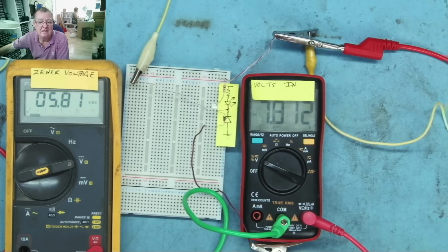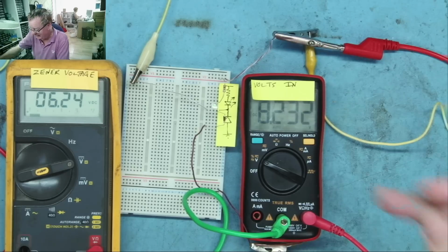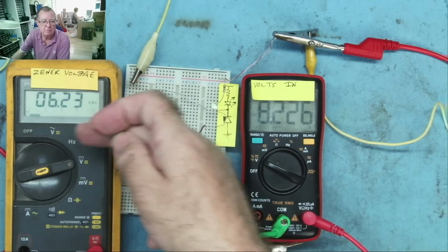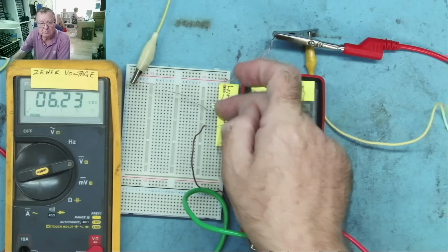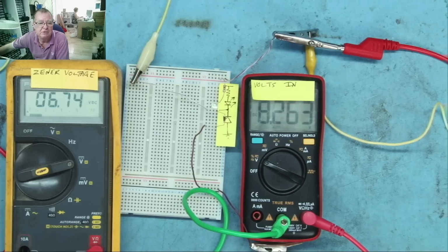And somewhere near here, this is a 9 volt. Well, there's a 9 volt supply, but there's only 6.2 across the Zener because of the voltage drop of the LED, which I keep mentioning, but at least it makes the point obvious by now. Somewhere here, the Zener will trigger there. Okay, so we can see now with about 10 volt supply, 11 volt supply, somewhere in that region, it triggers. 11.2. At 10.8 it's off, 11.2 the LED is on.